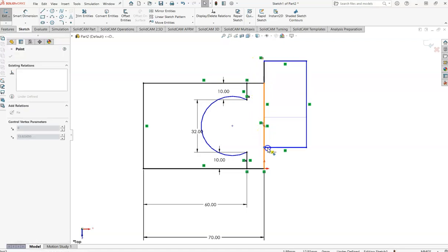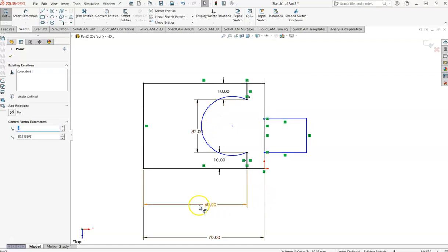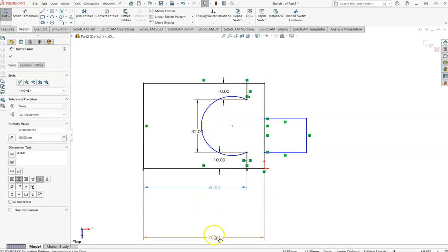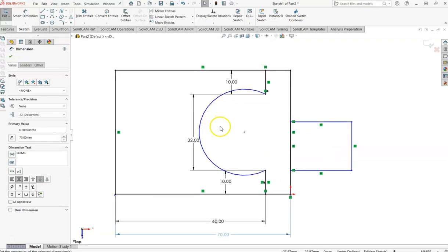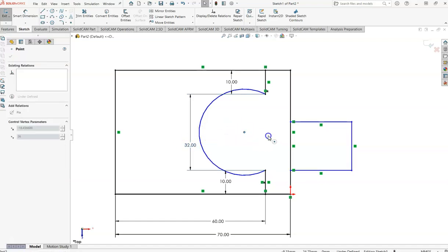Okay. Now, you can see some of my stuff started to overlap each other. So I'm just going to zoom in, just grab a blue dot and start to adjust some things here a little bit. Okay. Now, even though we determined what the diameter is, this circle or arc itself can kind of still shrink or grow a little bit, and that's all because of the center point.